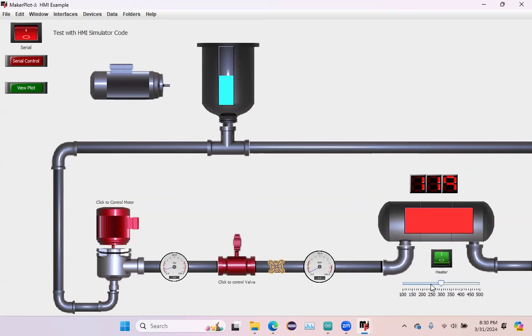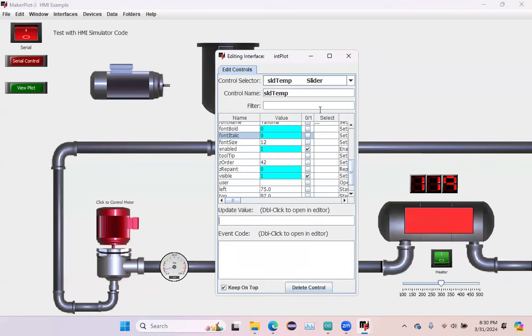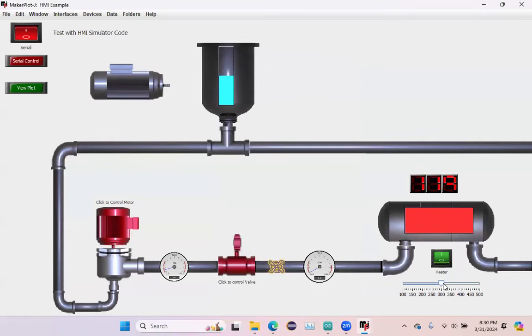The Arduino could send a code of F3, slide temp is equal to some value, and it'll update that from the Arduino for some set point. If we want to initialize and start things up at a certain level, or get certain parameters set up, we could do that. Okay. But basically, Arduino is just reading slide temp, and MakerPlot is setting that data back to be read by the Arduino in that big string. It's nothing too fancy there.